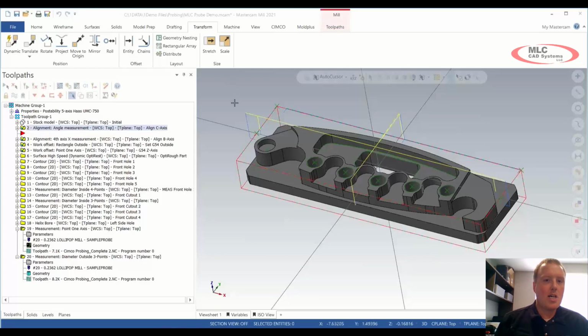Kind of continuing on and jumping into the remachining side of things here, what we can do is some type of in-process inspection. Now this could be, obviously, a broad scope of things on what it can mean for different people. But without trying to treat our machine tool as a CMM, we are able to utilize that probe in a matter of checking bore sizes and depths and widths, and also reassign toolpaths to tell it what, in fact, to do.